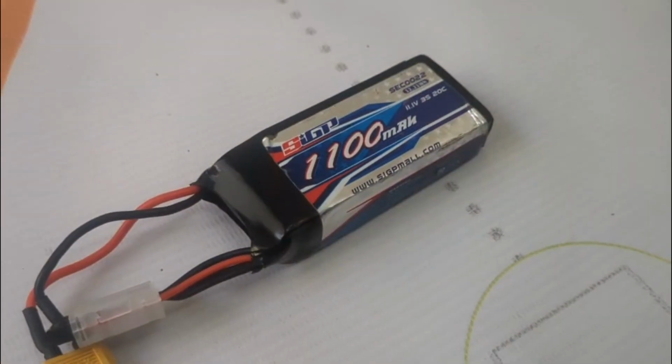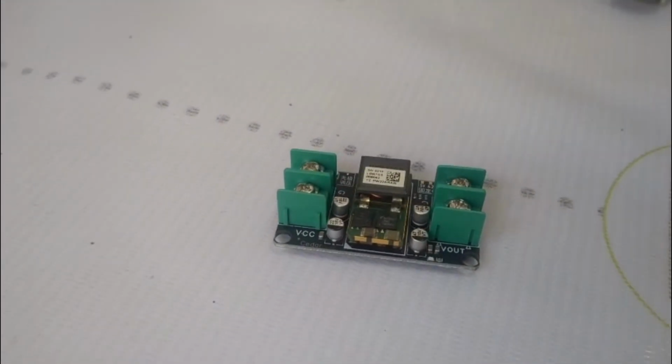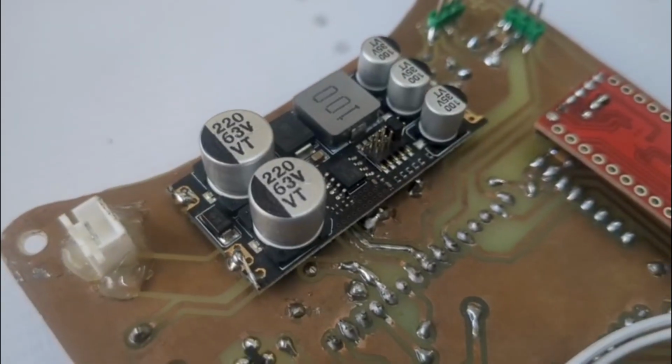The robot gets power from a 3-cell LiPo battery connected via an XT60 connector and a main power switch. To keep things clean and noise-free, a dedicated 5-volt converter powers the Raspberry Pi, the ESP32, and encoders, isolating them from the motor noise. A separate 5-volt 5-amp buck converter powers the servos, infrared LEDs, buzzer, and a few other components. The ESP32 monitors the battery voltage and warns us when the battery is running low.